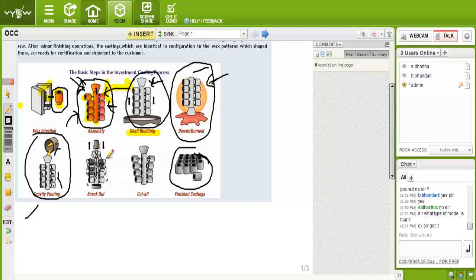After solidification, we just break the outer surface of ceramic, because ceramic is easy to break. If you give vibration, then it can be broken. And if we break this outer surface of ceramic, then the inner part is your product of the desired molten metal. When you get this, you cut from here. Then see, it is your final product, a small pipe.